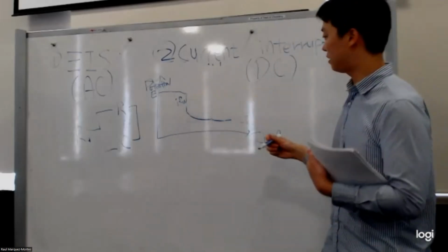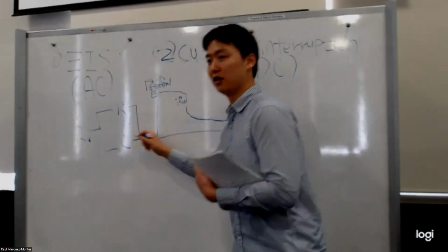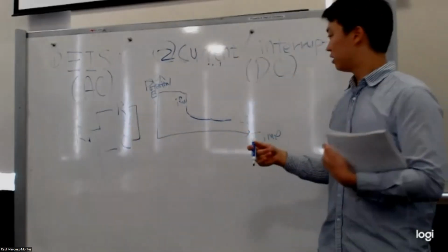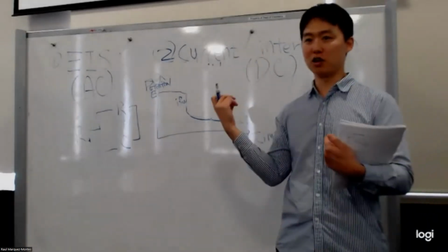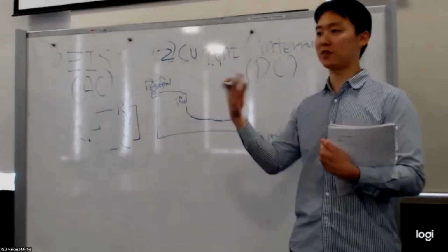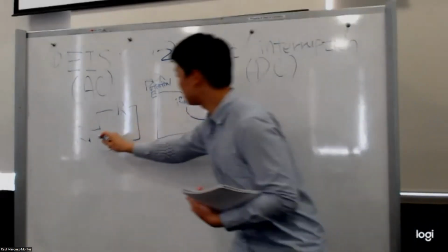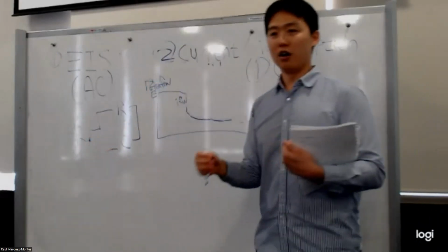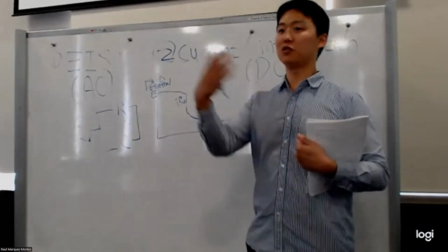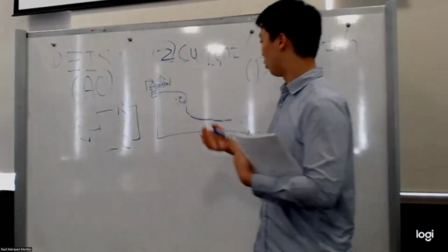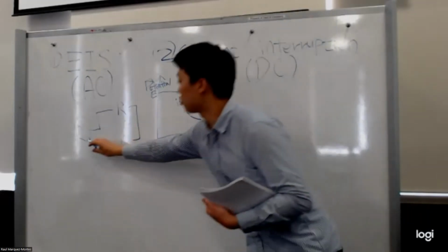The reason for that is we have this RC circuit, which has a capacitor term here. As I said before, to put the charge in the double layer or to draw the charge from the double layer, it always takes some time. So the same thing is happening in this case. The resistor term always reacts immediately to the applied potential, and it immediately shows the signal, like the current or potential drop. That's why it shows the immediate potential drop for this term.